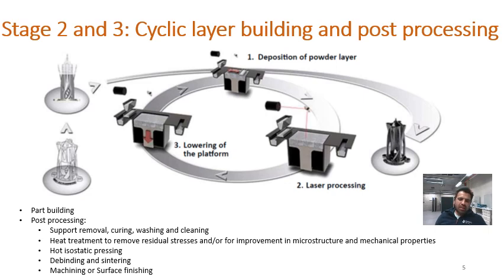However, the accuracy sometimes is not as required, and a machining step is done to mill the parts according to the required dimensions, or to achieve the required accuracy level. Sometimes surface finishing is done to achieve the final surface finish levels.